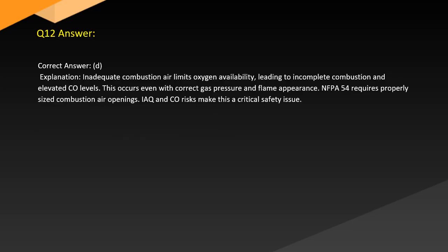Answer. Correct answer: D. Explanation. Inadequate combustion air limits oxygen availability, leading to incomplete combustion and elevated CO levels. This occurs even with correct gas pressure and flame appearance. NFPA 54 requires properly sized combustion air openings. IAQ and CO risks make this a critical safety issue.